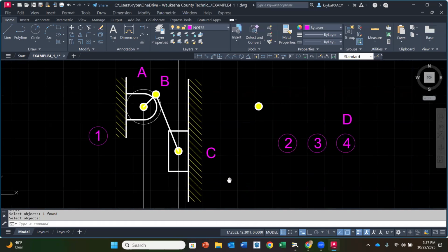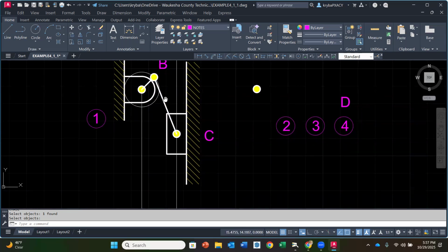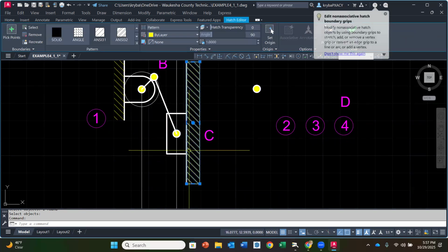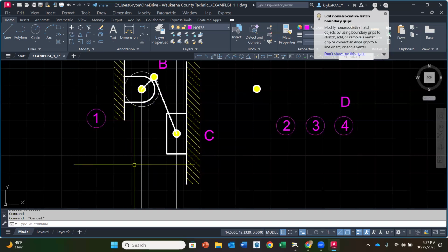Okay. So now that we are here, we are ready to take it to that next step to find the limiting positions. So we want to find out for link number 4 here, how far is it going to go down? That's where we're going to start first. Now, to do that, we are going to use the lengths of these 2 links, link number 2 and link number 3. And the place that it's going to be its furthest down is when, kind of following my cursor here, these 2 are going to be straight in line with one another. And their radius then is going to cross over that vertical line of action.